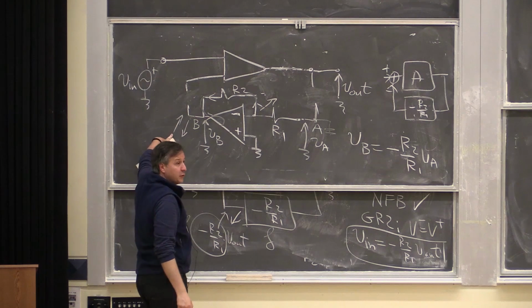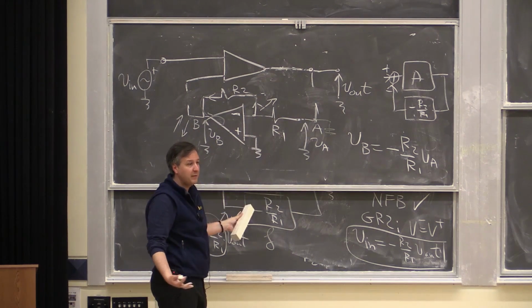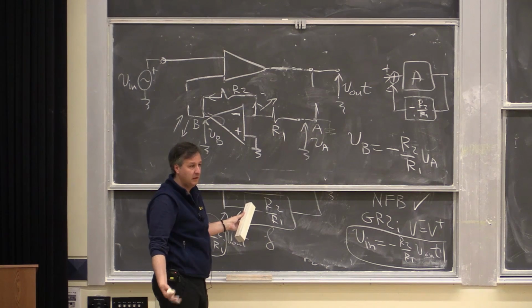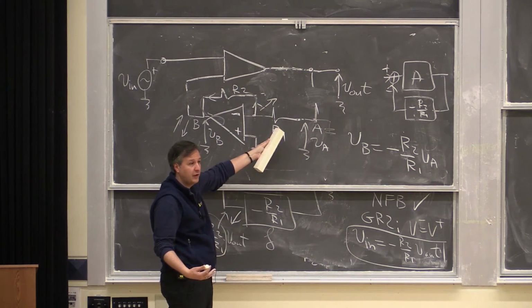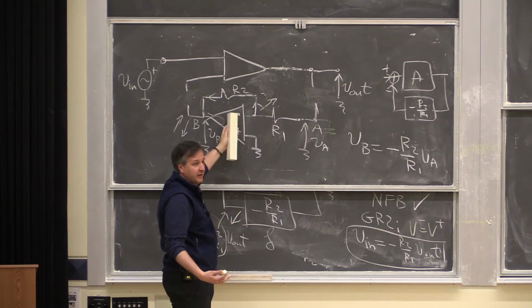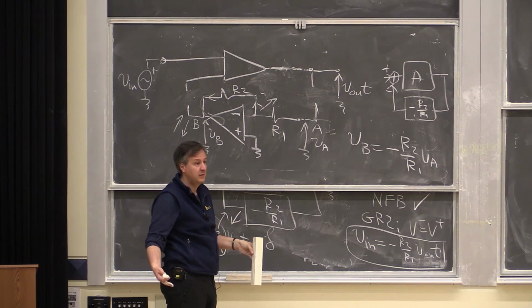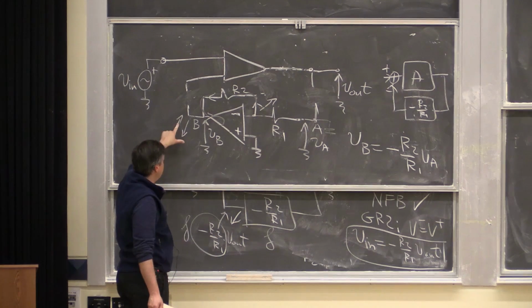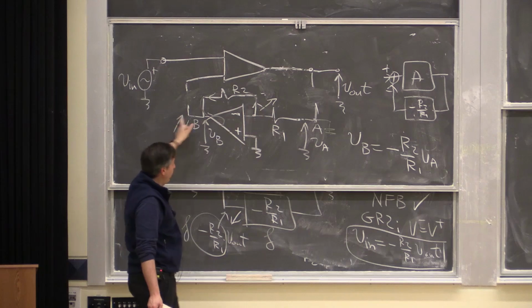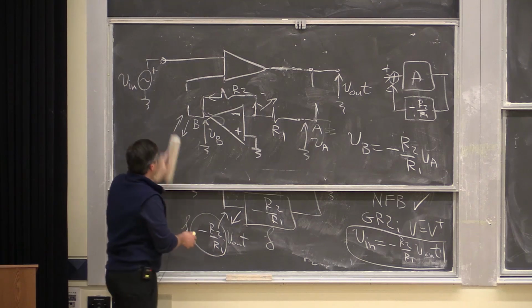Why do we want this output to increase? We want to make sure this circuit is stable. It's only stable when it's in negative feedback. It's providing a known gain that we can set by the feedback circuitry. So we're trying to put this one in the polarity such that it is in negative feedback. And therefore, the test for negative feedback is if I change the output, that it comes back as the opposite change. Okay?